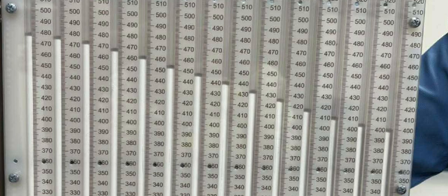3. Establishing steady-state flow. Keep the continuous water supply running until the water spilling over the overflow pipes remains perfectly constant. Monitor the wet boundary cutting through the dry sand of the dam profile. The phreatic line, the topmost water level line within the soil, is established when this boundary stops moving. Below this line, the soil is completely saturated. Above it, it is unsaturated.